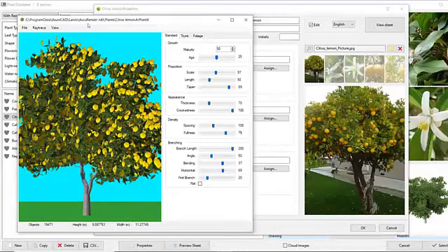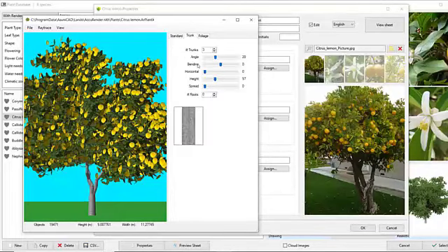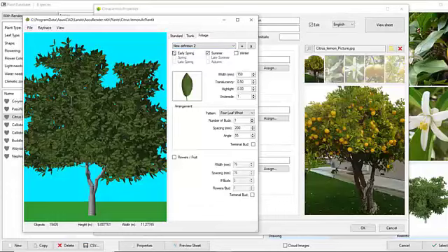So we can launch this editor to generate new plant files for the new species. Okay? We can assign some textures here, some foliage, fruits. We can save different settings according to definitions, and we're going to assign its definition to a specific season. That means that's how we can render the same plant one way or another, depending on the season we set into our document.